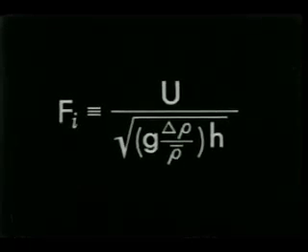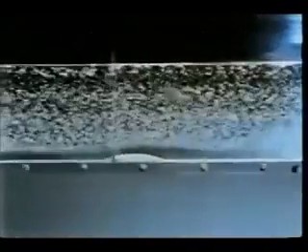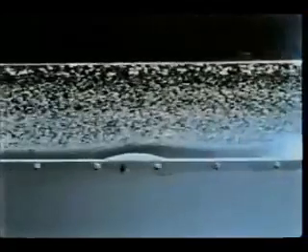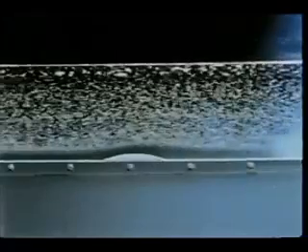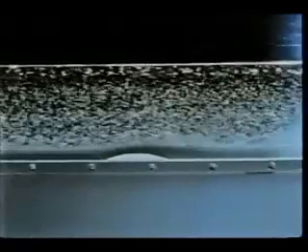Now we will look at some experiments in which we vary the internal fluid number and the obstacle height. Our experimental fluid is a saline solution in which the salt concentration, and therefore the density, decreases continuously with height. The tracer particles are neutrally buoyant polystyrene beads. The uneven distribution of beads does not reflect the density distribution. The density distribution depends only on the salt concentration and is more or less linear with height. Here is something analogous to the supercritical flow of water. The Froude number is high, and the fluid simply swells over the barrier as water does at supercritical speeds.